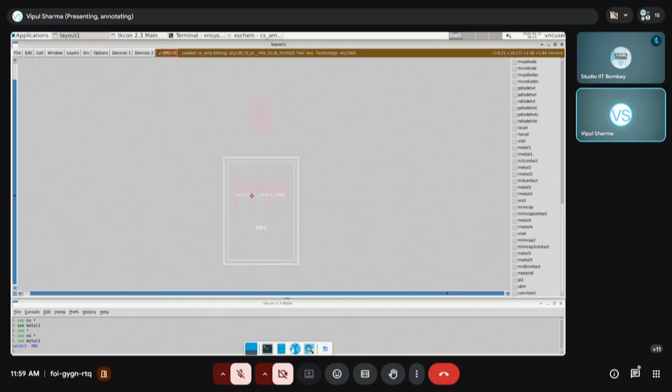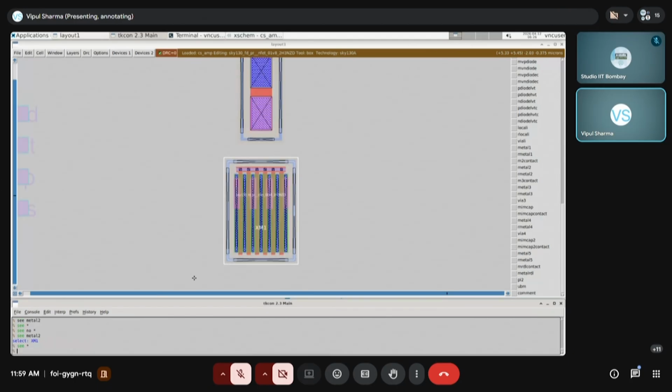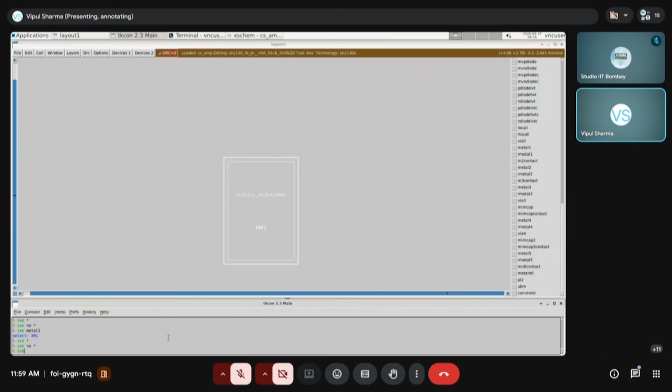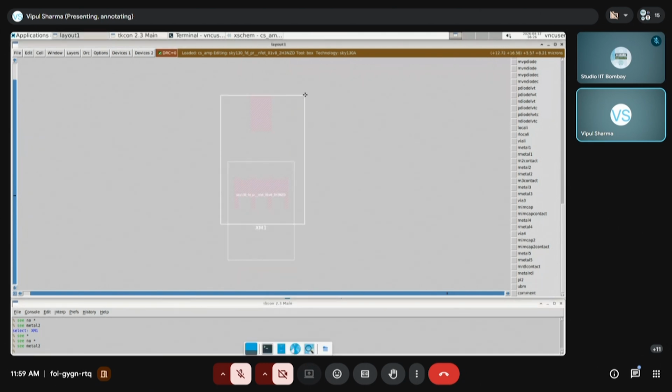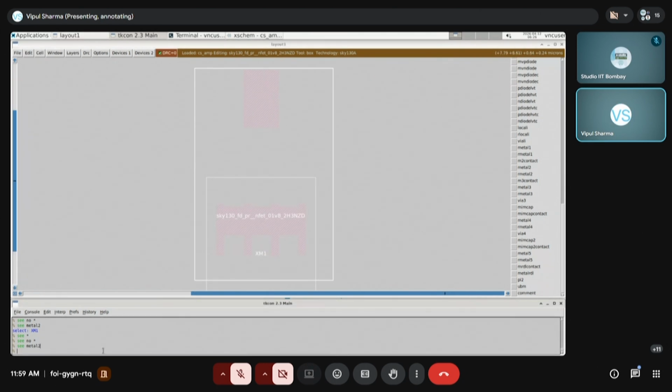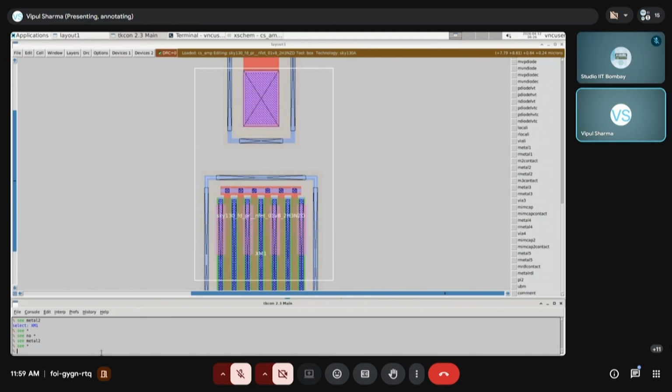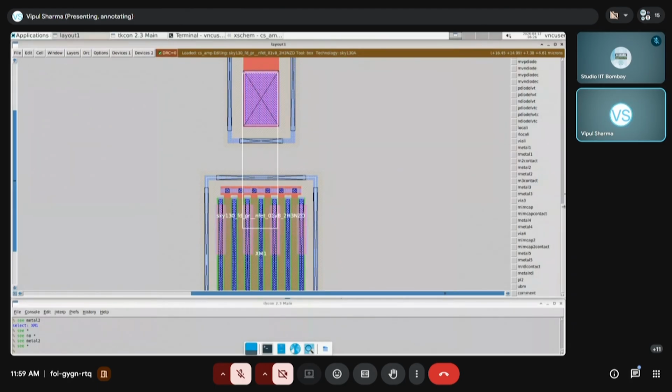and now the only step remaining is I have to make connection between. Yeah, it is there. And paint again, build a box between two regions where the connection has to be made, and paint it with metal 2 again to check it.